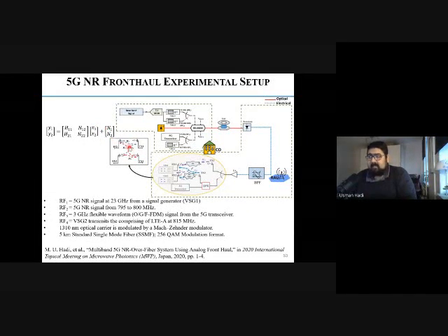So now we have the signal generation, and mind you that we are using two signals here, X1 and X2. So we have 3 gigahertz, 850 megahertz RF4, 795 to 800 megahertz here, and 23 gigahertz. So we actually have 4 signals, but we are using 2 at simultaneous points, because TX1, TX2 will interact with 2, and then RX1, RX2 will have a response from TX1 and TX2. So overall, there are 4 channels that you realize. So we have 4 RF signals in use.